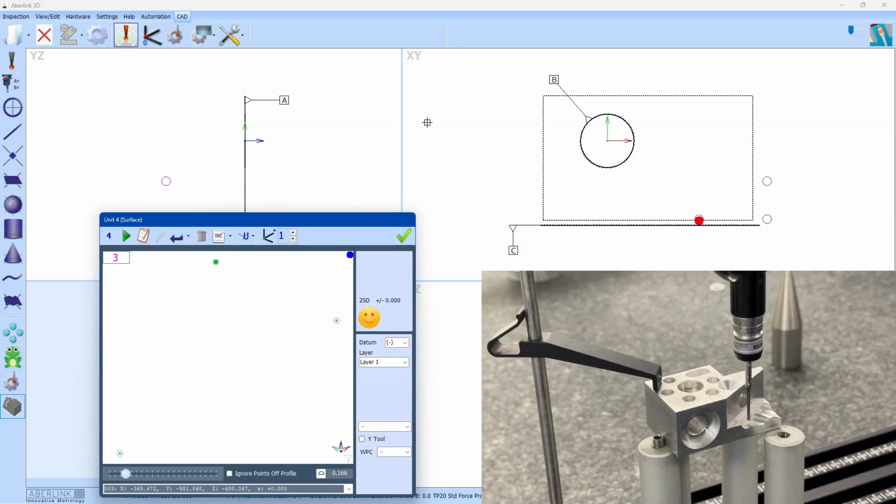I would like to highlight at this stage, it's generally a bad idea to program on the machine when measuring surfaces like this, as the vectors for the contact points are generally very bad. If you program from CAD, which will be in the next video, you will see how useful it is, as the probe can work out the correct vector via the mouse points. But hopefully it highlights how the function works in this video when on the machine.